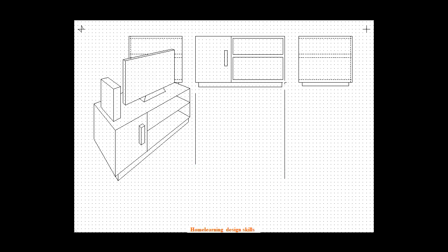If we take it from 45 degrees, so 45 degrees, if we want to get it in orthographic, where these lines come down, I'll take them across. So we just literally project the lines going down, where they go across, and in that way I know they're exactly the same length and distance as the other one. And this is what we're looking like from the top view.